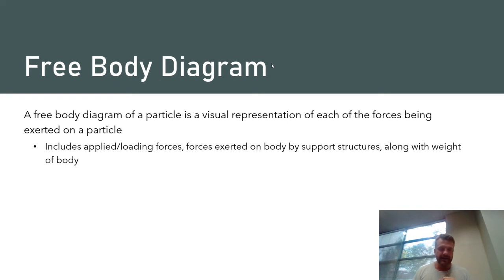So when we're looking at a free body diagram, what kind of forces should we expect to see? Well, we're going to see forces associated with actual applied or loading forces. So say, for example, I have my Subway cup here and I push upon it. I might see a force associated with the actual contact of my hand to the cup. In addition, I would see some forces associated with the support structures acting on the body. In this case, that would be the desk upon which it's sitting. I would see a normal force corresponding to the contact force that the desk exerts on the cup.